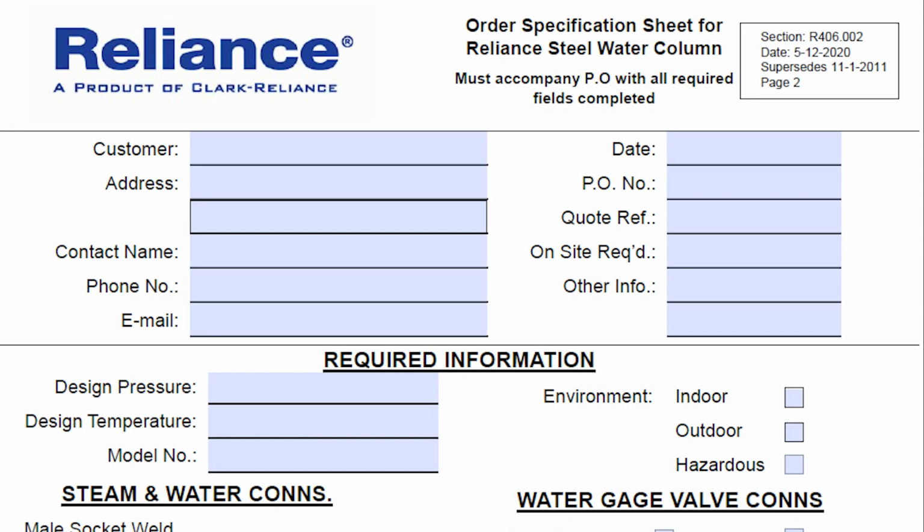So now that you know what is required for your boiler or pressure vessel, let's talk about the information needed to correctly specify the equipment. The maximum allowable working pressure, or design pressure and temperature of the boiler drum is necessary to correctly specify the equipment needed. This information can be found on the boilerplate that is attached to the drum or in the OEM documentation. It is important to note that this pressure, the design pressure, is different than operating pressure.